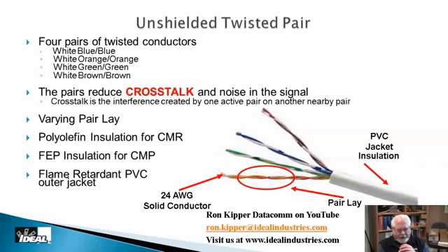Okay. Now, the insulation they use for the conductors in this cable can vary from manufacturer. They mentioned polyolefin here, but it could be other things. We'll talk about what riser cable is, and that's what the CMR stands for, or plenum rated cable. We'll talk about it here in a minute. And it's basically just the fire rating of the jackets, but we'll talk about that more in a second here too. And again, as a general rule, all these wires are generally 24 gauge. However, at Cat 6 and beyond, we've gone to 23 gauge on the conductors, but normally 24.